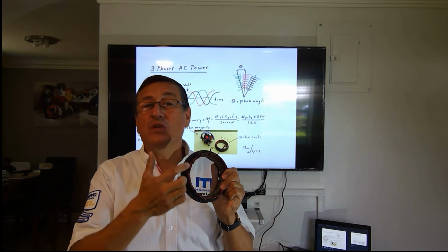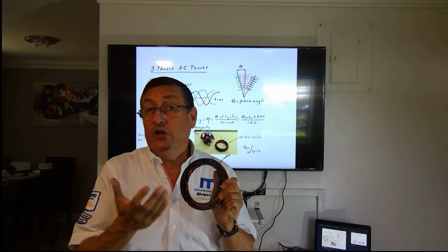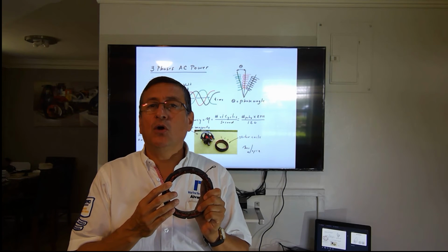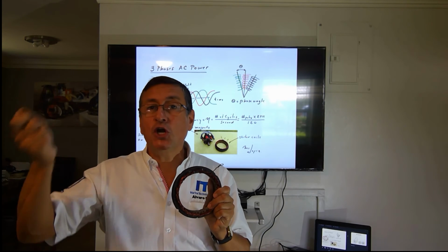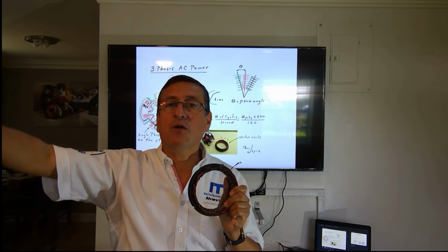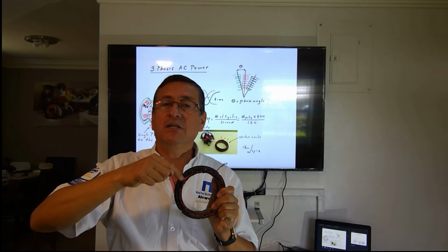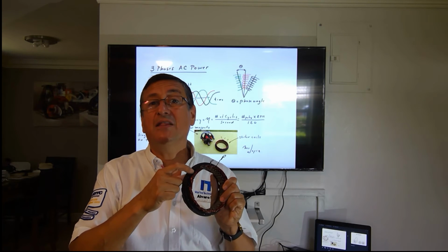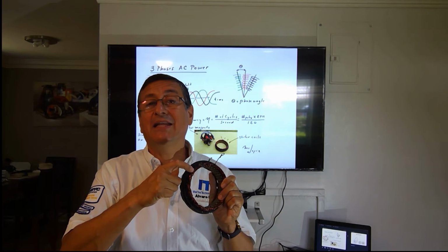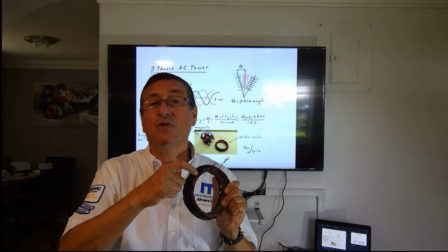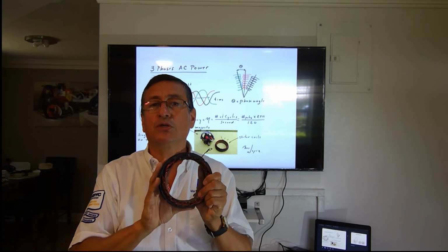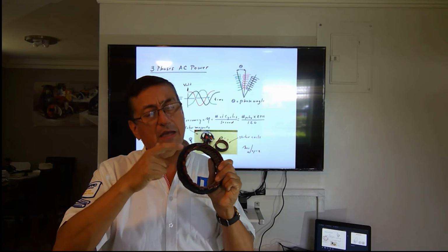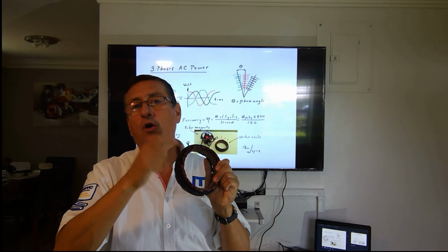How can that protection, that insulation, be damaged? For example, when you overload the generator, or when you produce a short externally in one of the equipments, probably the rotor or the stator is affected, and the temperature of the wire increases, and the varnish is cracked, and the electricity passes from one cable to the other one and produces the short. Don't forget, those wires are properly isolated. The wires, they don't touch one with the other one.